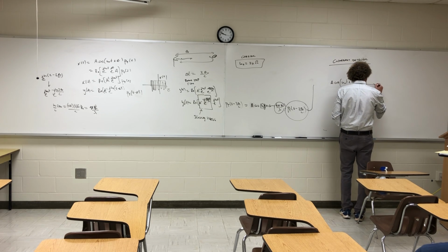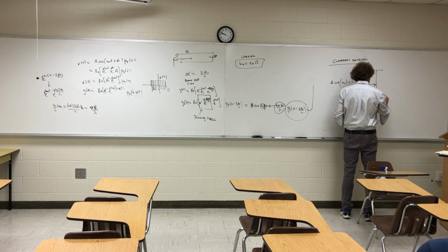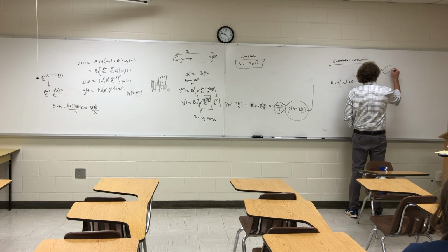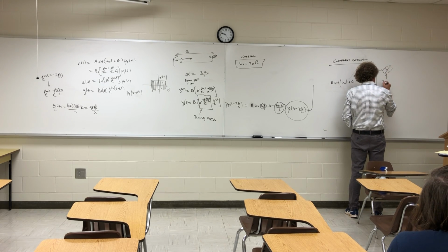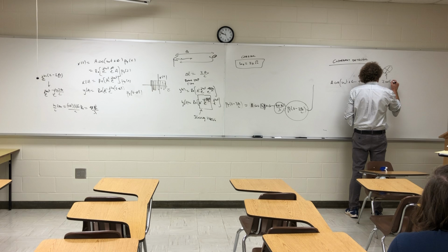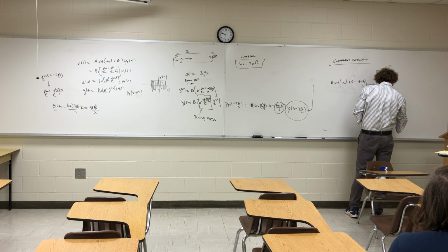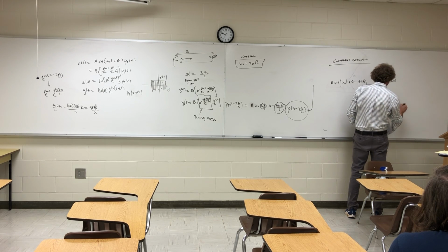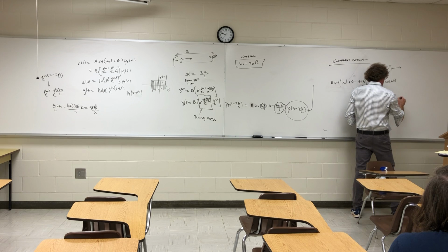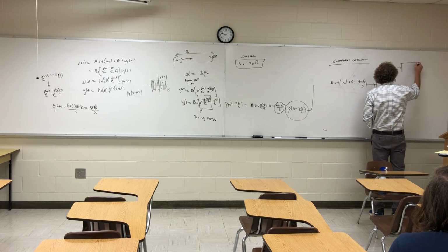It's going in, and he uses a splitter here and here. He'll take this and use a multiplier. He's going to multiply this by 2 cosine of omega naught t. Then he's going to multiply this one by 2 sine of omega naught t. This drawing's in the book, by the way. He takes the output of this and puts it through a low-pass filter.